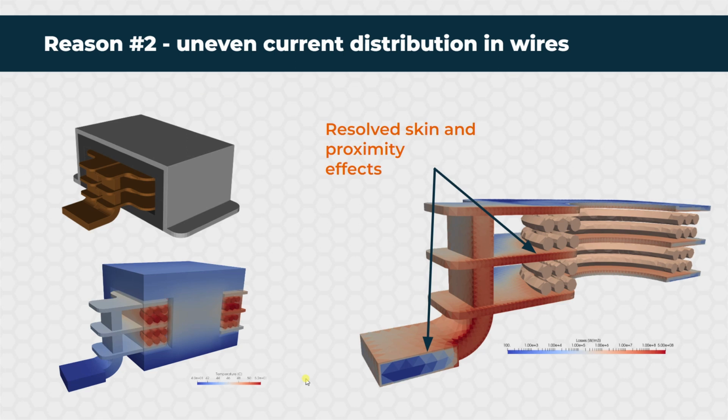The second reason why you would consider using 3D FEM is to treat complex 3D geometries. More specifically, oftentimes with planar windings, we get non-symmetrical turns that exhibit all kinds of strange effects.